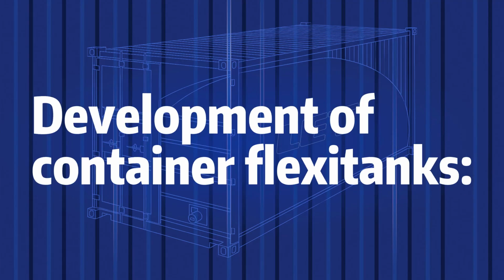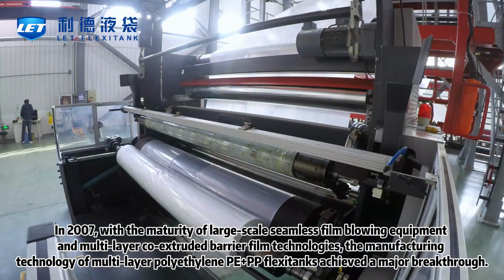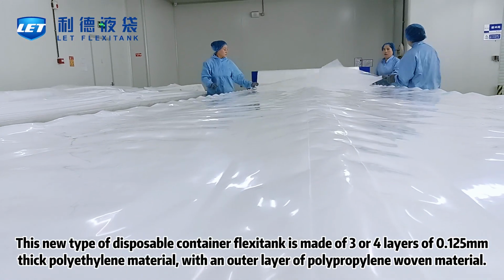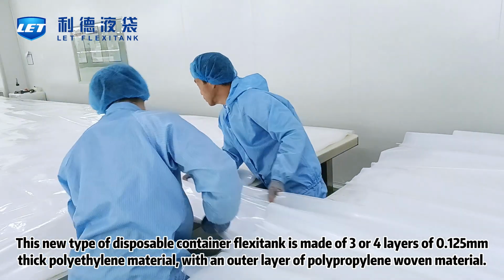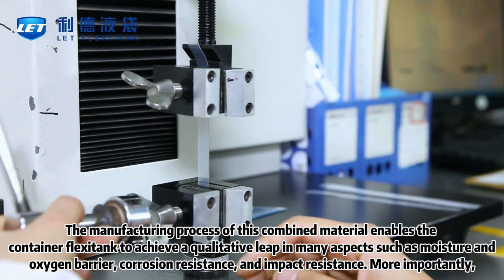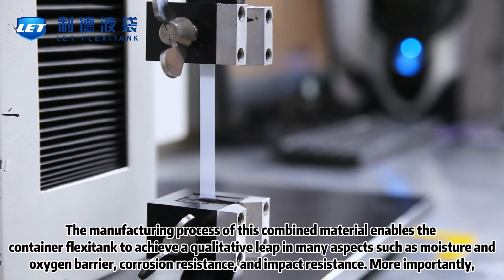Development of container Flexitanks. In 2007, with the maturity of large-scale seamless film blowing equipment and multi-layer co-extruded barrier film technologies, the manufacturing technology of multi-layer polyethylene PE plus PP Flexitanks achieved a major breakthrough. This new type of disposable container Flexitank is made of 3 or 4 layers of 0.125 mm thick polyethylene material, with an outer layer of polypropylene woven material. The manufacturing process of this combined material enables the container Flexitank to achieve a qualitative leap in many aspects such as moisture and oxygen barrier, corrosion resistance, and impact resistance.